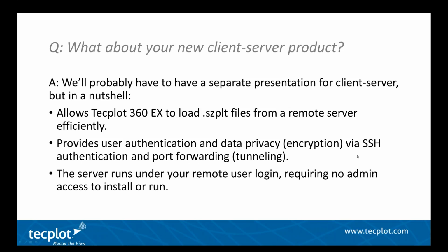SCPLT file. Although files written with later versions of the file may not be compatible with earlier versions. So we're backwards compatible. We can always read older files with the newest Tecplot, but not necessarily read the newest files with the oldest Tecplot. So you're probably best off with a new version of Tecplot. And from then, of course, writing PLT files remains an option with Tecplot. So once you've loaded the SCPLT file, you're free to output it as PLT if you want.